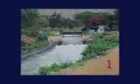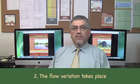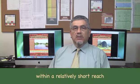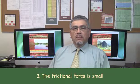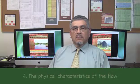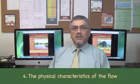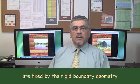Rapidly varied flow has the following characteristics or features. 1. The curvature of the flow is such that the pressure distribution is not hydrostatic. 2. The flow variation takes place within a relatively short reach. 3. The frictional force is small compared to the other forces acting. 4. The physical characteristics of the flow are fixed by the rigid boundary geometry.